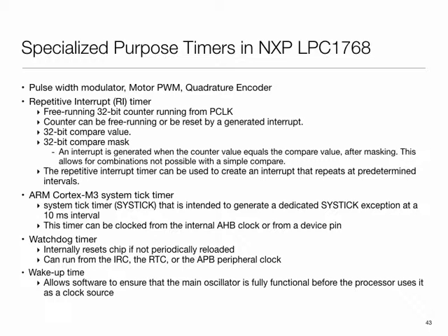There is something called a repetitive interrupt timer, which basically lets you generate interrupts at repetitive intervals. Since every operating system worth something usually ends up having to maintain time, there is usually a timer which is specifically meant for the OS to maintain its tick.